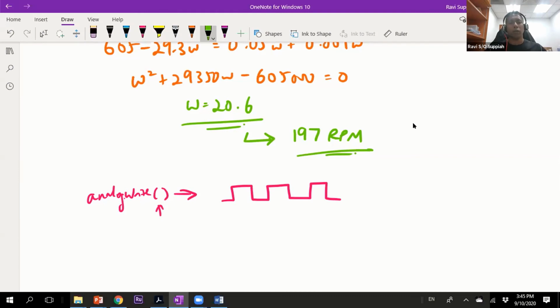On your Arduino board, some pins have a tilde sign on them, and only those support PWM output. It happened that the two pins we were using in the studio had PWM capability, so I could use analogWrite.